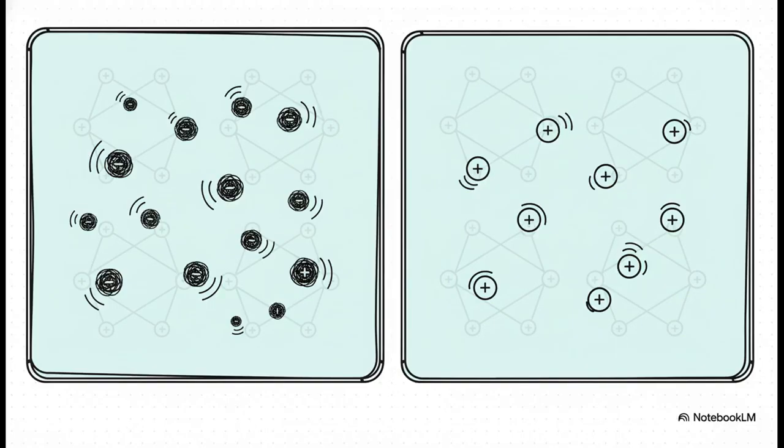So here's the big takeaway. Doping gives us this incredible, precise control. By adding a pentavalent impurity, we get a material that's swimming in free electrons. By adding a trivalent impurity, we get a material that's full of holes. We can literally custom tailor the electrical properties of the material on demand. This right here, this is the breakthrough that allows us to build complex circuits.